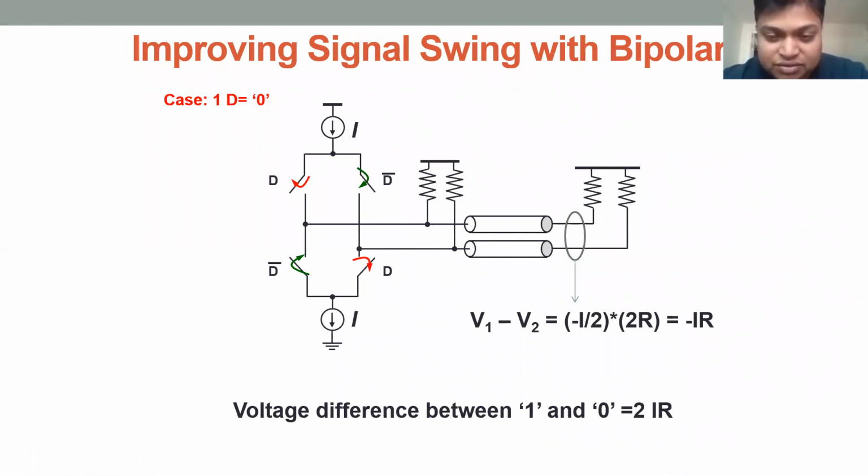So now if we follow this thing, there is one thing still a bit inefficient about it. And that part is because, see, it's always I/2. It's I/2 because the transmitter side has some sort of termination.